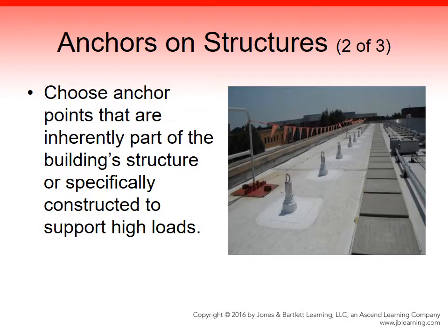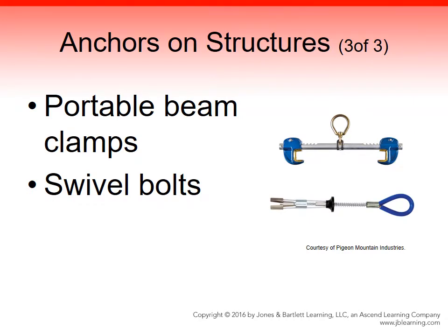Newer tall buildings usually have permanently installed anchor points on the roof for window cleaning equipment. Some industrial sites will often have pre-engineered fall protection anchors over the entrances of confined spaces. Many devices such as portable beam clamps and removable swivel bolts can quickly be installed to existing structures. Artificial high directionals, made popular for wilderness cliff rescue, adapt well to create strong anchors.